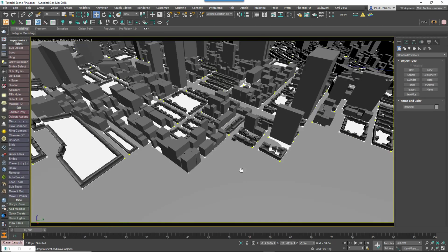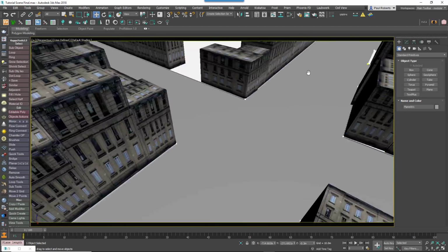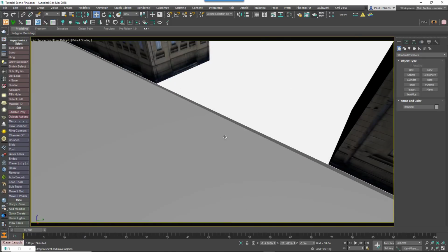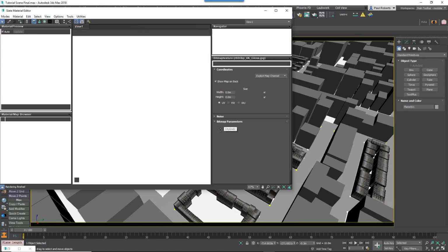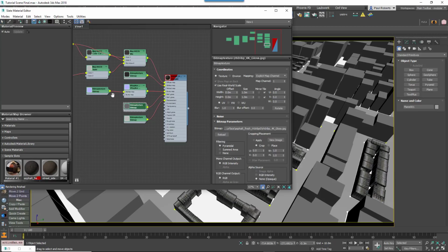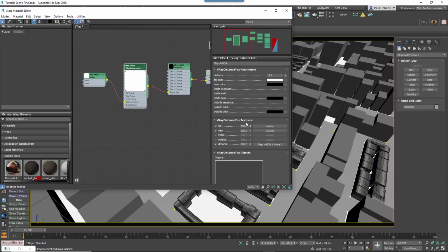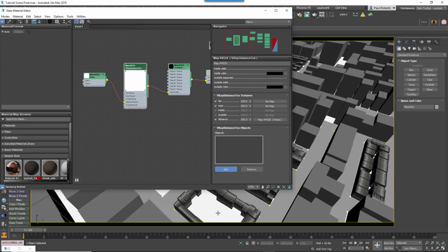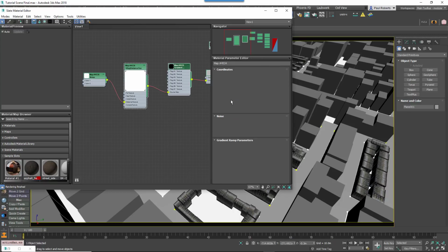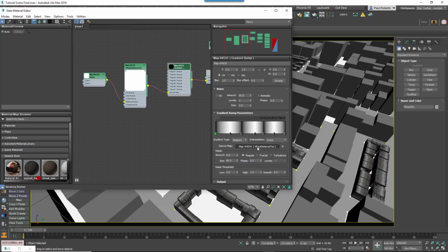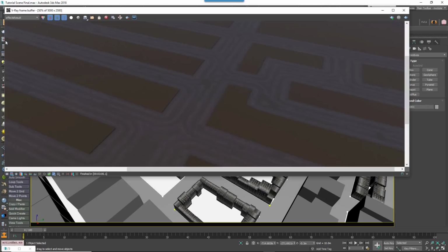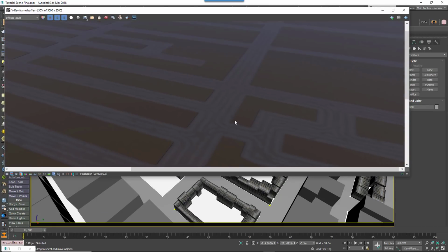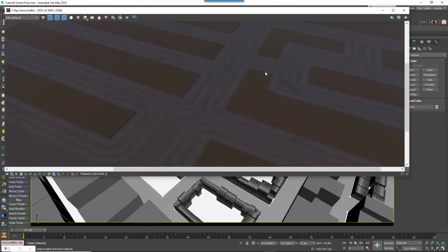The city grid spline can also now be used to add cars to these streets. Note that here, instead of modelling and texturing roads, you can use a simple plane to cover the entire area, and then we've used a V-Ray distance texture to parametrically add wear and tear based on the distance of the surface from the city block. There's not time in this tutorial to go into that technique, but the material is included in the downloads so you can have a look and see how it was done.